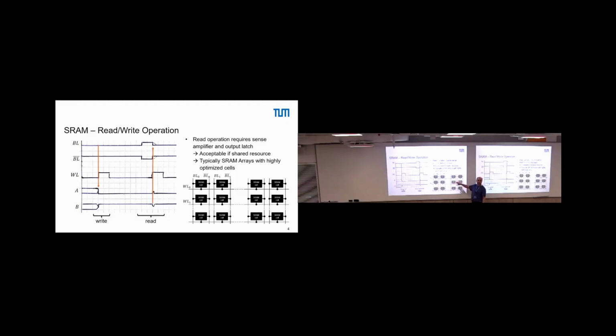If you have a large memory, then you spend this overhead, because this overhead is shared among all the cells. And the relative overhead compared to the memory size gets small, so you can use the SRAM as a fast, effective memory. Good. That's approximately where I ended yesterday.